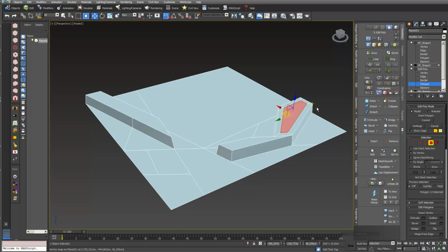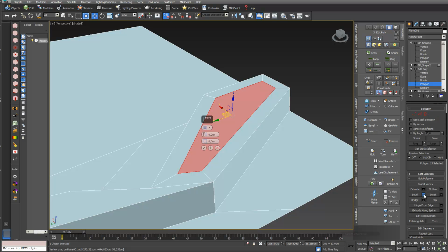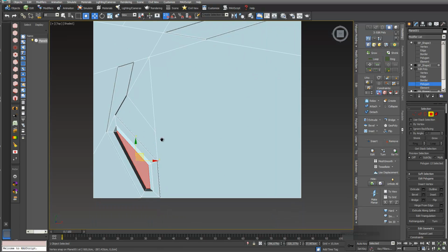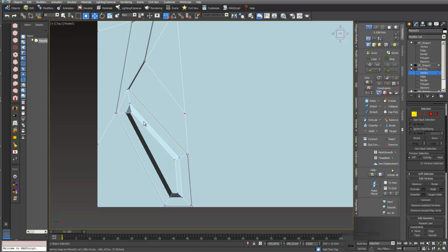I just go into model and just do everything in one go now. I just go into bevel, and I just extrude it to the inside, somewhere like this, and I go a little bit smaller, so I have a little bit of a shape. And obviously, if I go into my top view, I can also choose the hierarchy, my vertex hierarchy, and my snap function I just switch off, otherwise I can't do it properly. But you can see that I can define the areas.